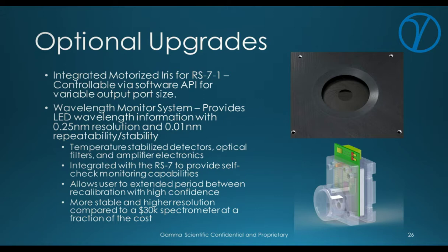We have repeatability of 0.01 nanometer resolution, which historically I would not even report because it's not a significant digit for most spectrometer systems, but we actually have that type of repeatability and stability using a photodiode-based system with optical filters built into it. So it's a proprietary design that we've come up with. There's no diffraction grating. There's no array of pixels, CCD or CMOS, anywhere. It's just 3 photodiodes with specialized optical filters on top of them.